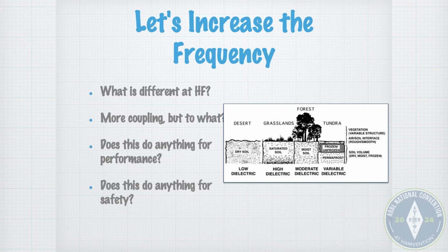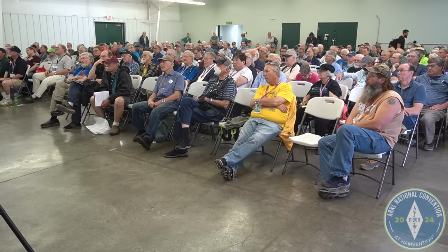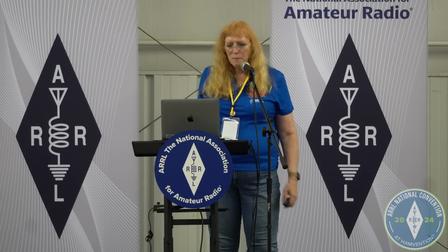Now if we increase the frequency, we get other effects. We have different kinds of soil, and they have these dielectric effects. And so they start acting more like a capacitor. So as we increase the frequency, you'll get more coupling perhaps. It depends. This might have interesting implications for your antenna system. You might see the pattern shift around as you change frequencies, based on the kind of dirt that's underneath your antenna, especially if you have a low horizontal. You'll see this because you get a lot of those kinds of fields. You get current mirroring, which tends to push the pattern around quite a bit more than the charge mirroring.